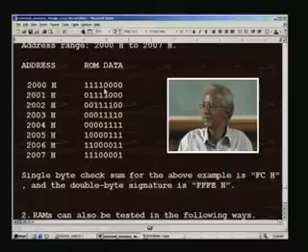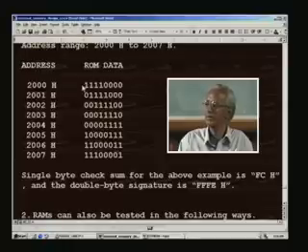In this example, the single byte signature, if you compute manually, you will see that it is FC in hexadecimal, and if it is a double byte checksum, it is FF FE. And how to get this double byte signature is you put this second byte here and treat the whole thing as a 16 bit number.